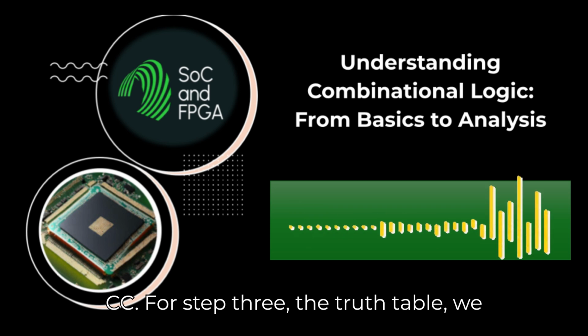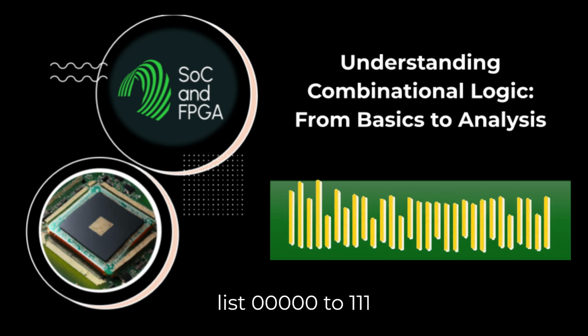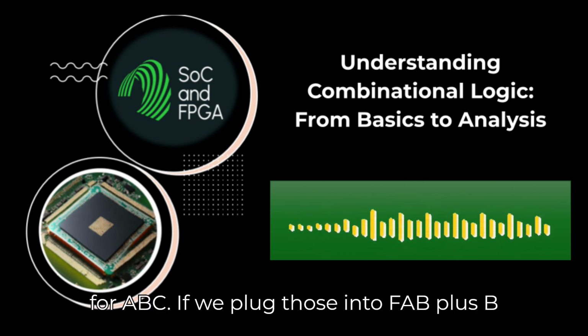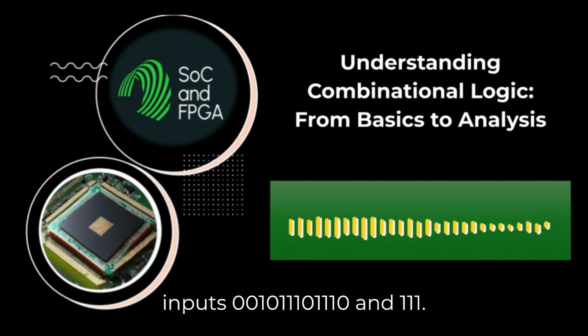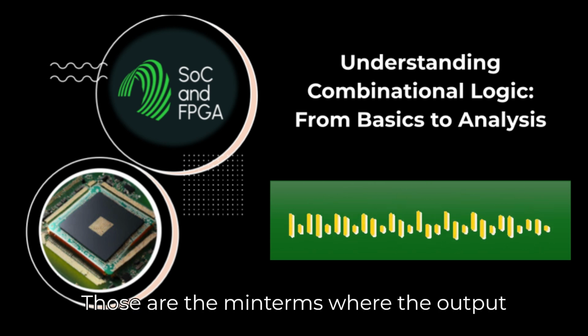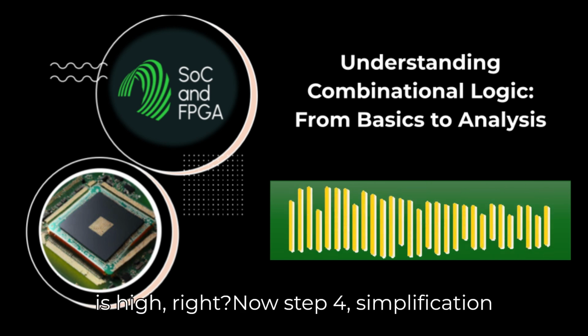For step 3, the truth table, we list 000 to 111 for ABC. If we plug those into F = AB + (B + C)C, let's say we find F is 1 for inputs 001, 011, 101, 110, and 111. Those are the minterms where the output is high. Right. Now, step 4, simplification.